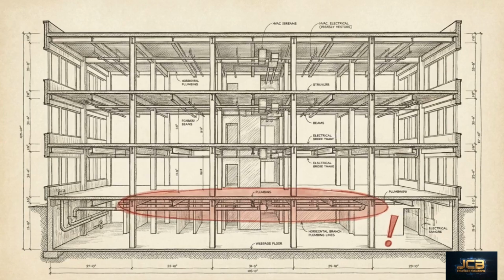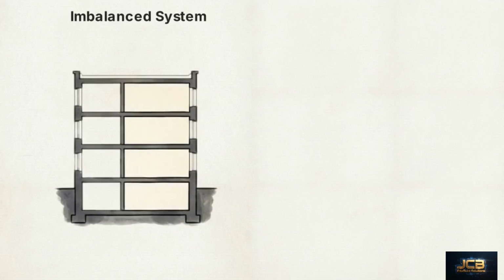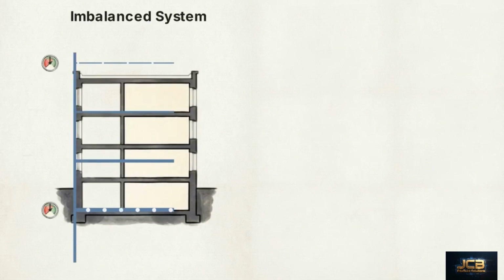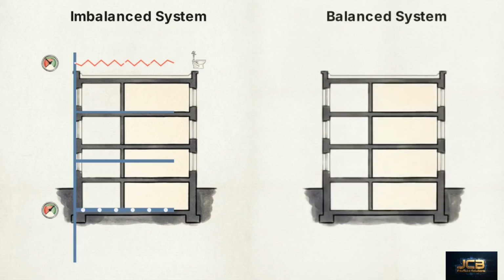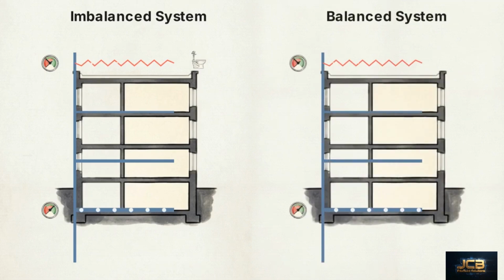There is a final hazard to avoid. If an engineer uses that same maximum permissible friction loss to size the branches on the lower floors, it will create a systemic imbalance. Lower floors naturally have higher local pressure because they are closer to the main. If sized uniformly, those lower branches will draw water too easily, starving the upper floors of volume during peak demand. Engineers solve this through deliberate system balancing. They intentionally select smaller pipe sizes for lower branches to increase local friction, or they install throttling valves to artificially restrict the flow, equalizing the system pressure from bottom to top.